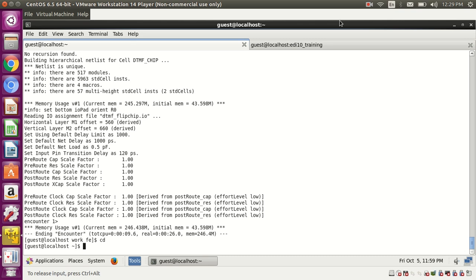So if there are two parallel nets, if M1 is there and parallelly one more M1 is there, and those nets are parallel for some 100 microns, with shape 1 and shape 2 of M1 only, or M1 or M2 in the same metal, straight and parallel for 100 microns, then the tool will calculate and, for net 1, add some extra cap, and for net 2 it will add some extra cap.